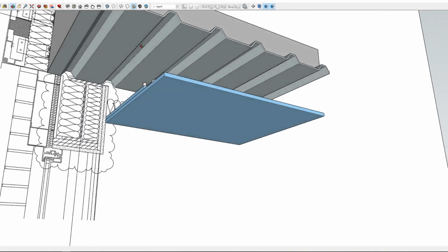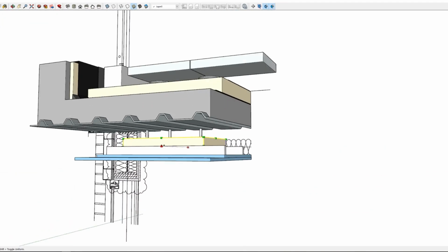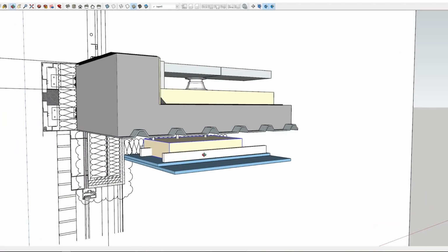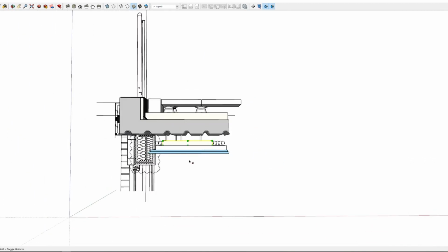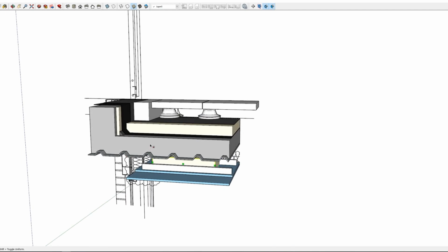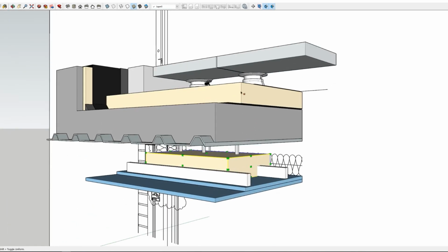And then what that does is, obviously it gives you a nice plasterboard finish, and that's acoustic, it gives you acoustic separation. Now in this instance we have treated it like it's between apartments, because there will be people walking on there. So the client particularly questioned, do we need 2 lots of insulation there? But one's doing the thermal, one's doing the acoustics, if you like.